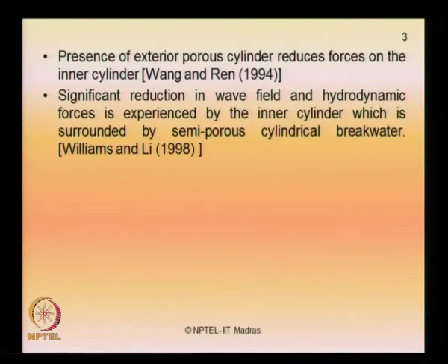There is also a significant reduction in the wave field and hydrodynamic forces experienced by the inner cylinder when it is surrounded by what we call semi porous cylinders. This application has been tested in breakwaters by Williams and Lee, and they have quantified that there is a reduction in the hydrodynamic forces on the inner cylinders when they are covered by semi porous outer layers in breakwaters.